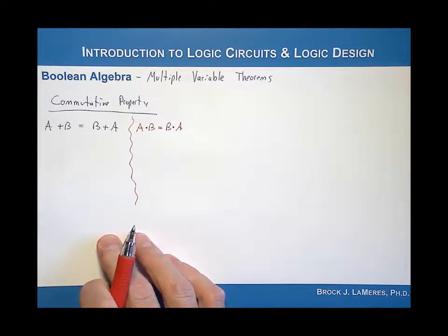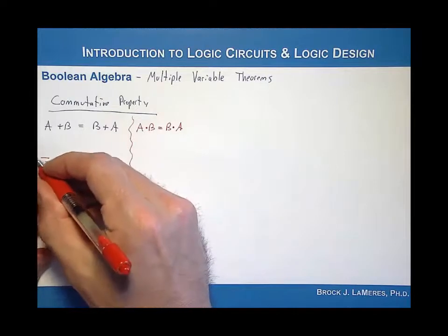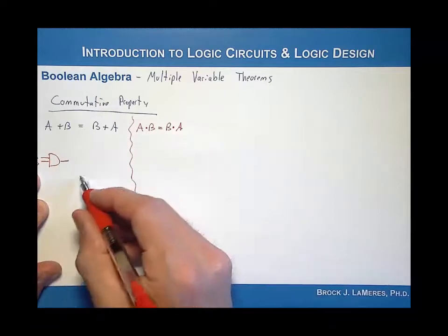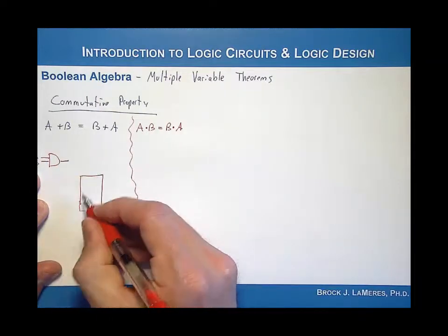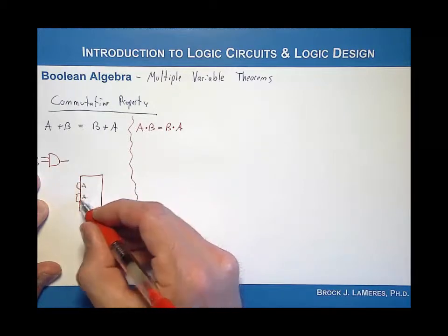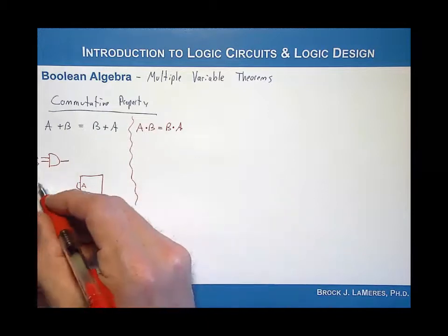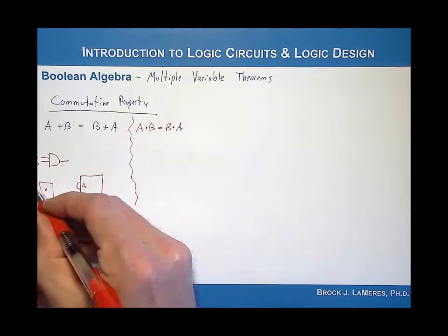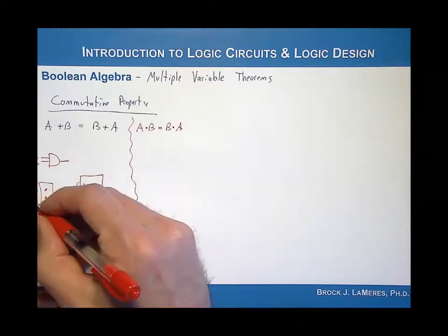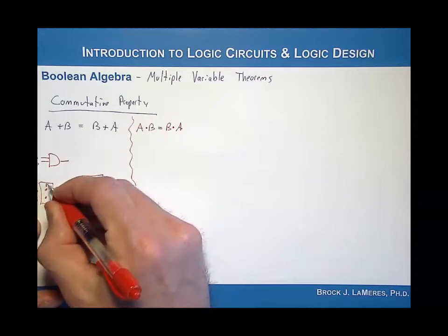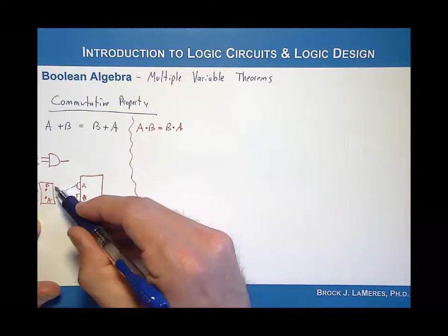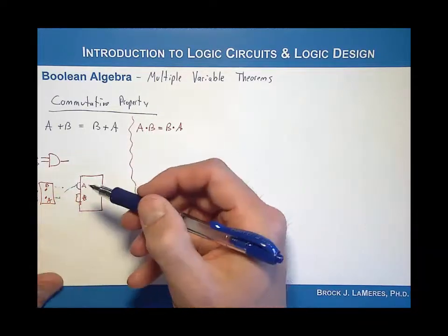So if you had a circuit where you were implementing something with A and B ANDed together, and this was the schematic, and then you went to a particular part, and the part looked like this with a pin here and a pin here, and this was where A and this was where B was. And you had a connector, for example, where B came in here and A came in here, and you were going to route these. You'd notice that this came over to here, and this needed to cross it. So if you were using a single routing layer, you wouldn't be able to do that.